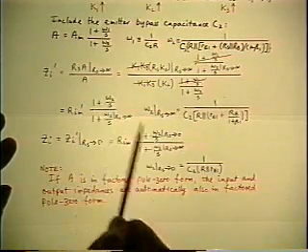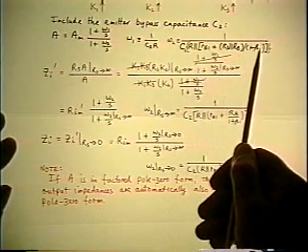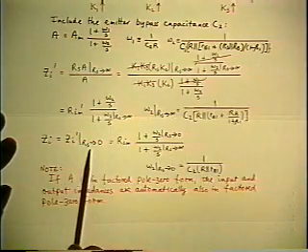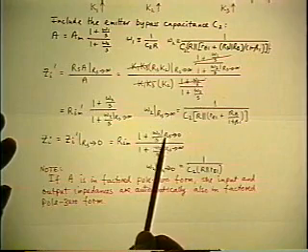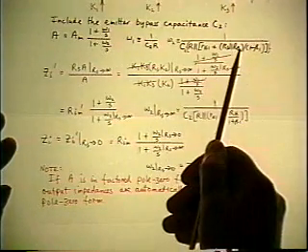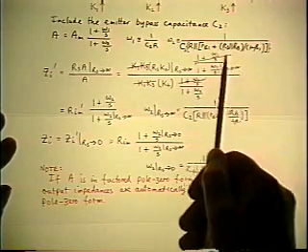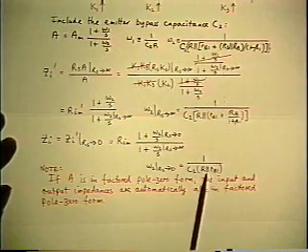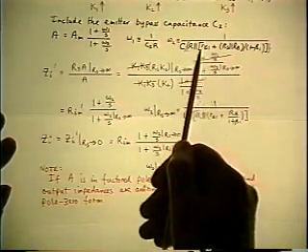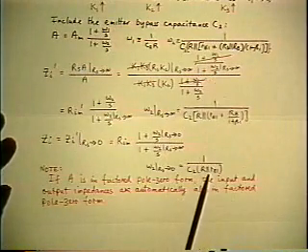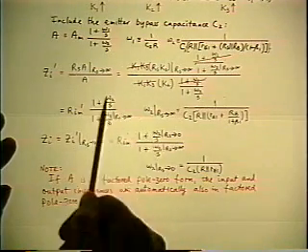The omega 2 in the numerator is the original omega 2, which still has Rs in it. So when you take the limit of Rs goes to 0, you get another new corner frequency. Omega 2 as Rs goes to 0, which is the original omega 2 with the entire second term absent. Because if Rs goes to 0, it kills the parallel combination. So you're left just with the R parallel RE1. So there's another new corner frequency that comes from the numerator.